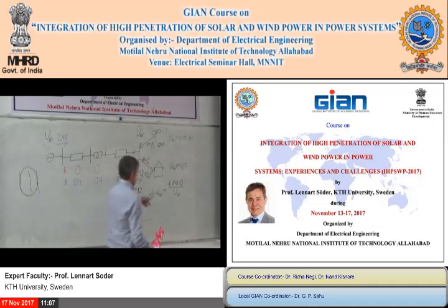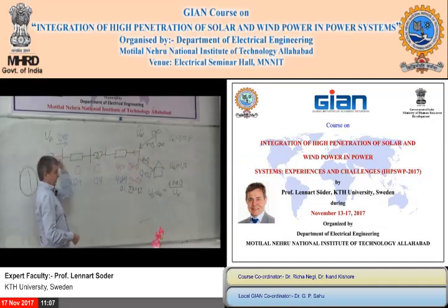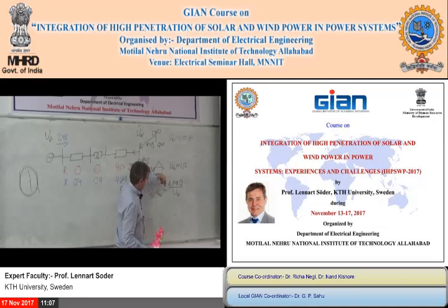You can see it this way. If you look at this system, you are sending P in that direction, and you are sending Q in that direction. The voltage difference is R times P plus X times Q. R times P is increasing the voltage, while X times Q is decreasing the voltage.